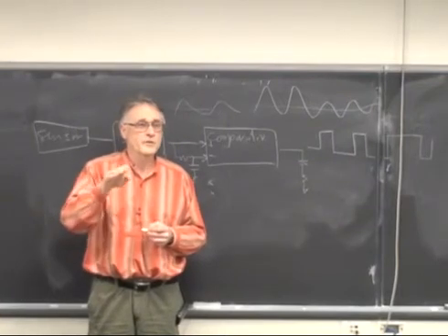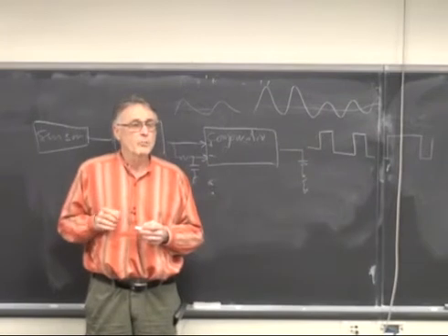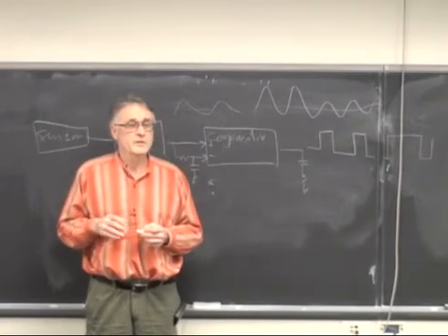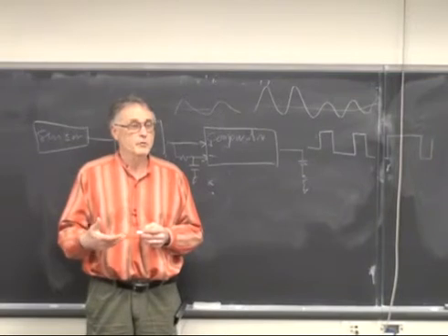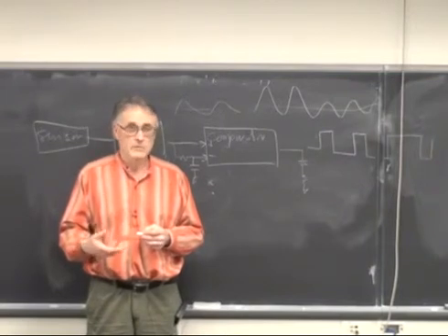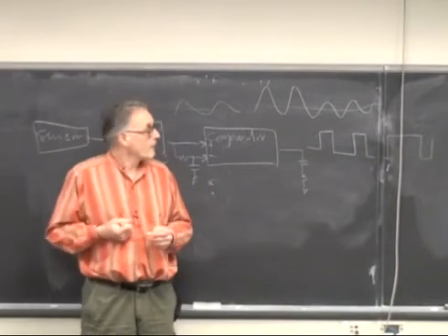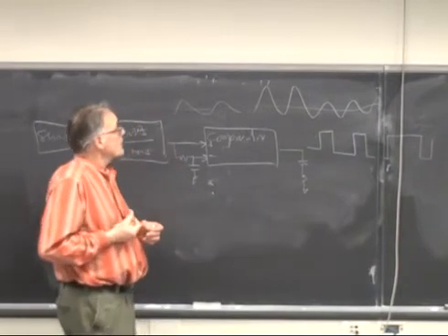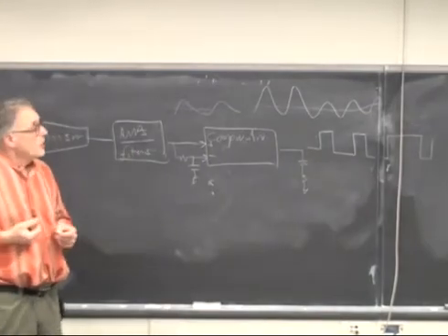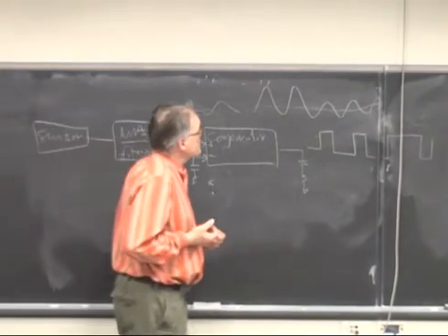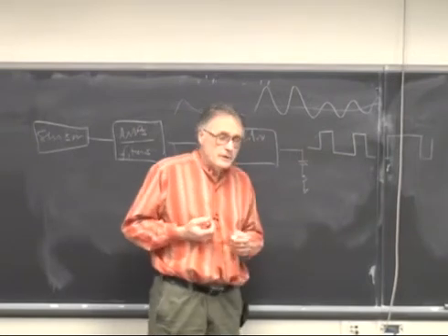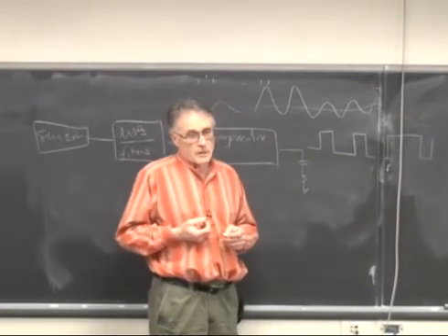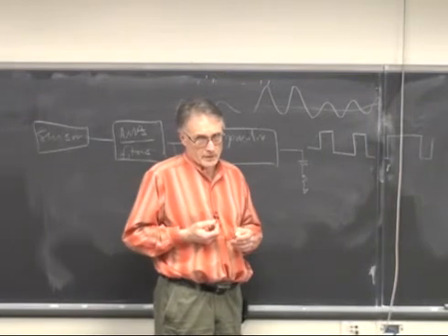It adds up the number of, if you had all pulses the same size and then you integrated the area under them, the number that you integrated would be proportional to the rate. Why couldn't you feed this to a capacitor to charge it? And you could, if the duty cycle were constant independent of frequency.